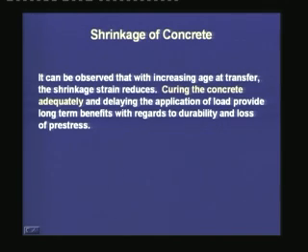Curing the concrete adequately and delaying the application of load provide long-term benefits with regards to durability and loss of pre-stress. Just as we have seen for creep, similarly for shrinkage, if the concrete member is properly cured and then if the pre-stress is transferred, then the shrinkage strain will be less, the durability of the member will be better, and the deflections will get reduced.